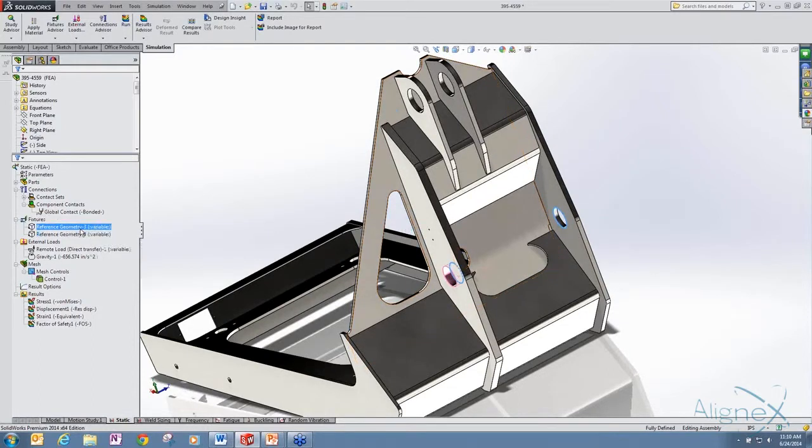So we're fixing those with geometry that prevents any axial movement or radial movement of these circular edges, but we are allowing rotation of those edges, so they can sort of twist. But again, with linear statics, we need to make sure everything's in static equilibrium.